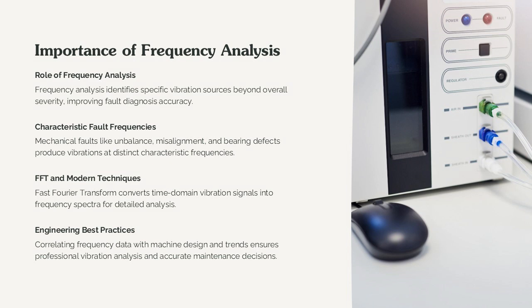Without frequency analysis, vibration assessment is limited to severity evaluation and cannot support accurate fault identification. This may lead to unnecessary maintenance or missed failure modes. Modern vibration analyzers use fast Fourier transform (FFT) techniques to convert time-domain signals into frequency spectra, enabling detailed analysis. Engineering best practice requires correlating frequency data with machine design, operating conditions, and historical trends. This disciplined approach distinguishes professional vibration analysis from simple vibration monitoring.